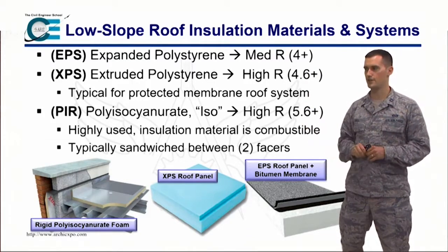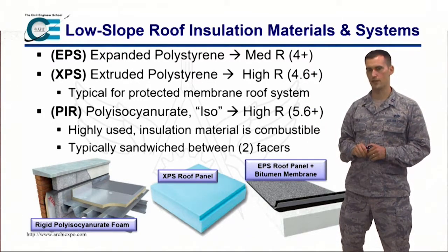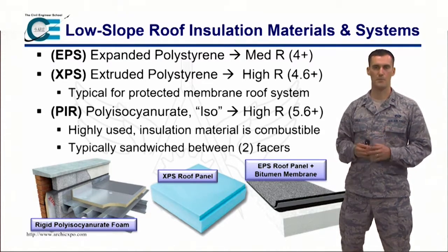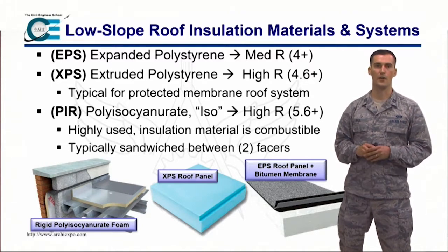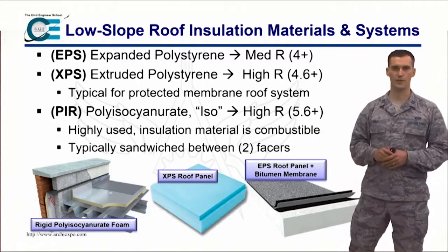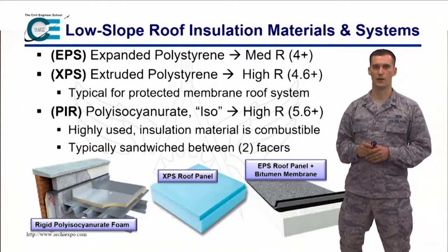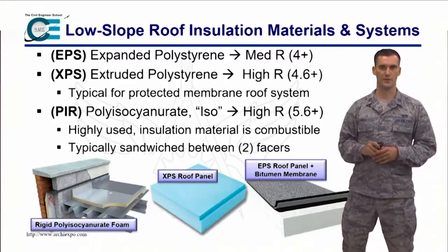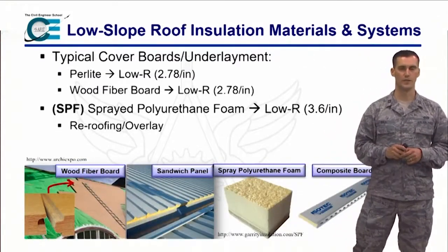These are the heavy hitters that we typically go with, that you're typically going to see in low slope roofs, and then in a pitched roof setting, you're going to see a non-rigid or flexible insulation installed. And so isoboard, that's where we're going to get the most for our money. But XPS is definitely what you're going to want to use in an inverted roof there.